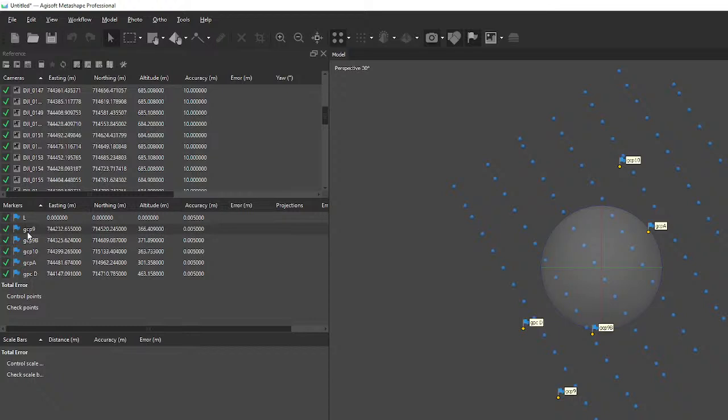Now, these are my markers or my ground points, and these are the coordinates that come with it. One of the tricks that you need to focus on is that the easting up here should match with the eastings on the markers. So if you flip and you bring northings here and you have eastings here, you will have some mistakes in terms of your alignment. And this is the ground elevations, as in our Z, and this is the accuracy of our point.